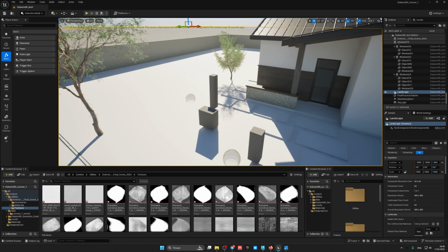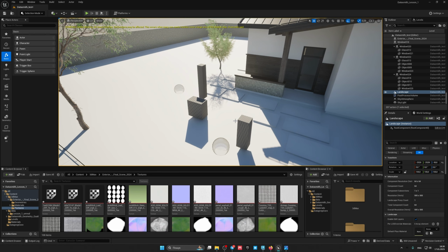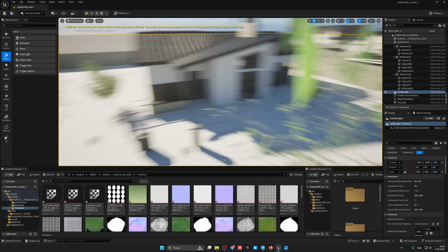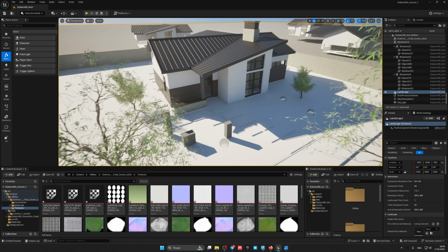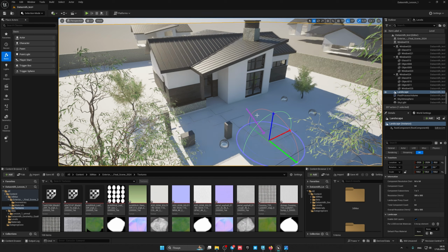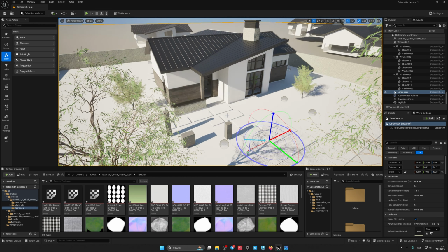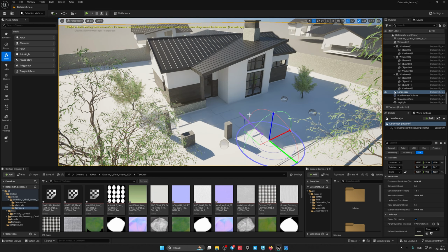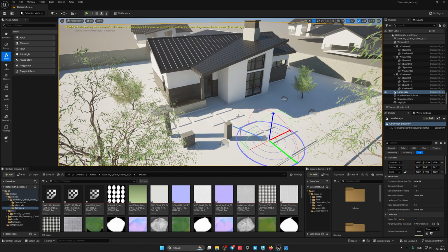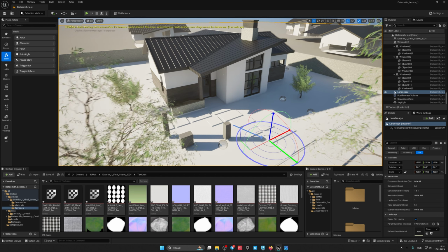And these objects immediately appear in this scene. So you can work in 3D Max, search for shapes, model something, and check how it looks in Unreal. It already appears with lighting, because here we can easily control our light. We will talk about this later, but this is how you can work in real time, creating objects in 3D Max and see how they look immediately in Unreal.